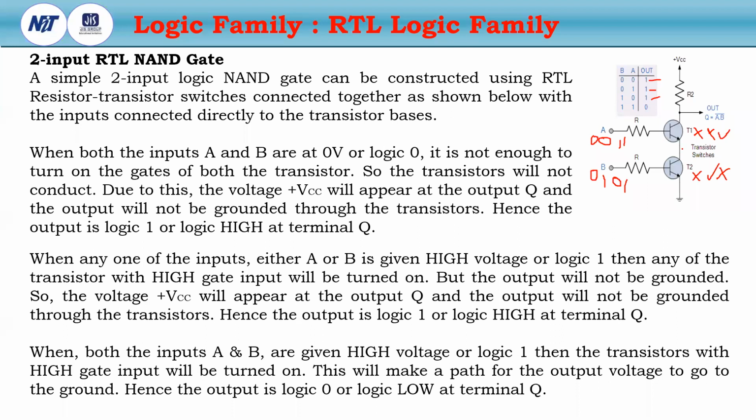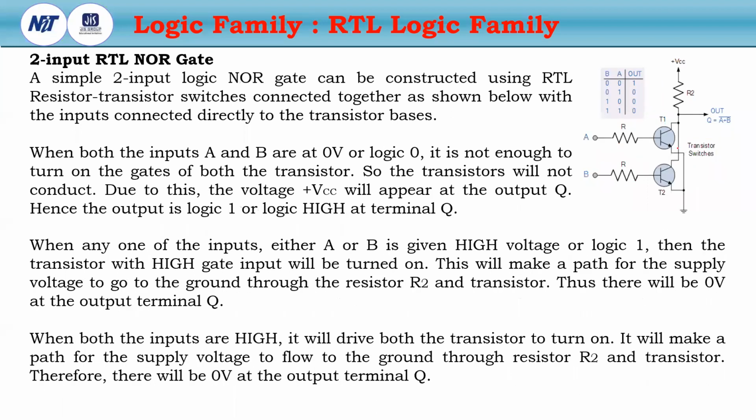Also the NOR gate, if these two are in parallel mode, so if both are 0, then both are cut off. So there is no current produced, so the output will be at VCC.